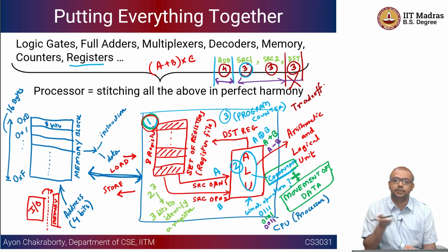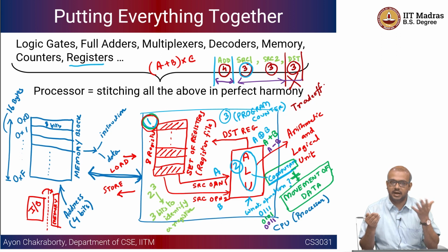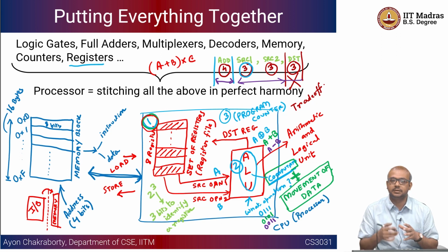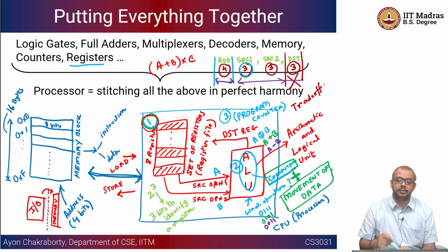You always start with the 0th instruction, which could be at memory location, let's say 10. Then the program counter is going to point to 11, which basically means the first instruction is going to be executed. Then it goes to 12, which is the second instruction, then the third instruction, and so on, unless there is a change in the flow control. Suppose you call a function, so then there is a branching. Or you write an if-else condition, so if something happens, do this, or if it doesn't happen, you have to skip that and go to a different instruction. Those are special cases that are going to be handled. The program counter, which you can also call an instruction pointer, basically points to the instruction that is going to be executed next.